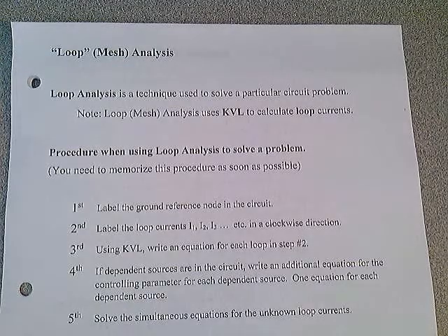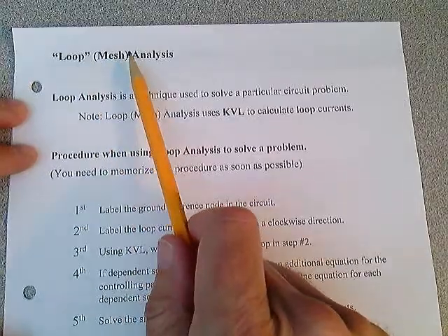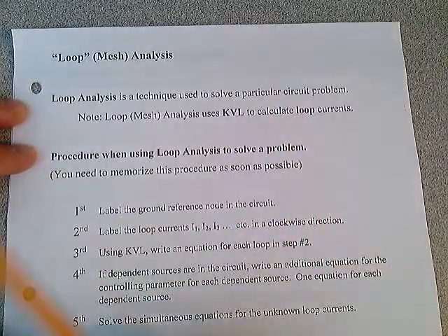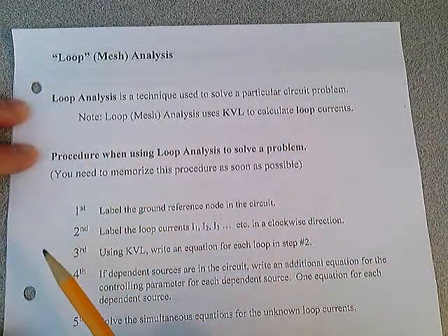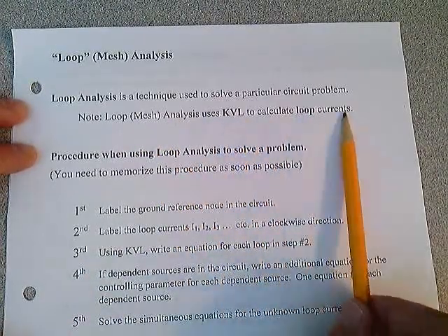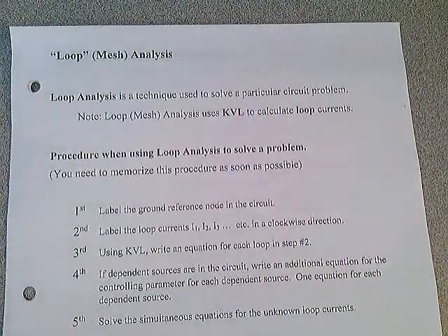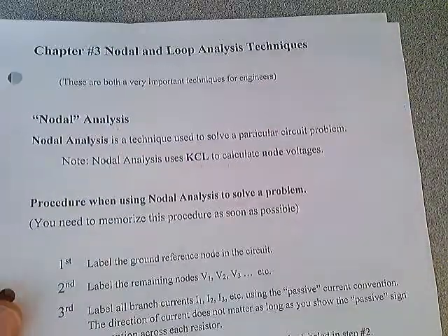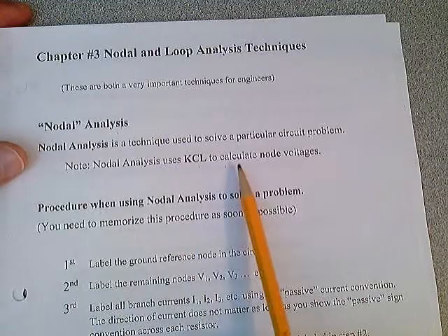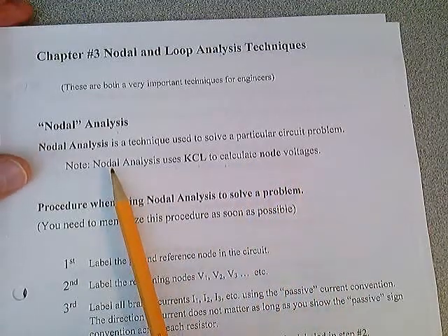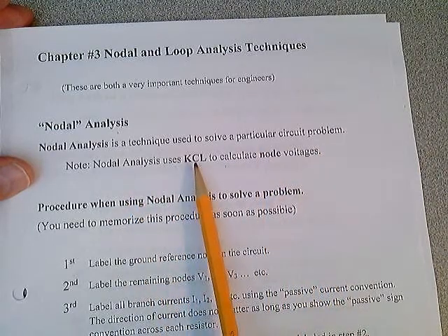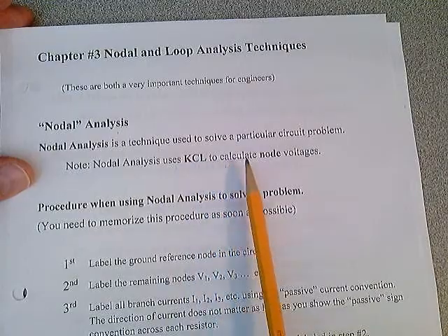We're going to start out by looking at page 50, loop analysis, sometimes referred to as mesh analysis. Loop analysis is a technique used to solve a particular circuit problem. Note, as we go through this, you'll see that loop or mesh analysis uses Kirchhoff's voltage law to calculate loop currents. I want you to compare that to what nodal analysis did back on page 44. Note, nodal analysis uses Kirchhoff's current law to calculate node voltages. I want you to think about that when you read it, because I want you to understand nodal analysis uses Kirchhoff's current law to calculate node voltages,